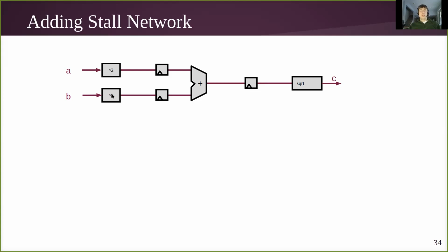So what do we need to do to introduce stall into our pipeline? First, we need the ability to hold on to the values in our flip-flops. And we could represent that two ways. One, as I've done here, is to explicitly recirculate the value through a mux. The other would be to control the clock that controls the flip-flops, which inherently are capable of holding values.